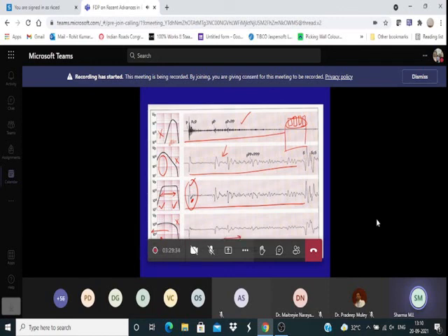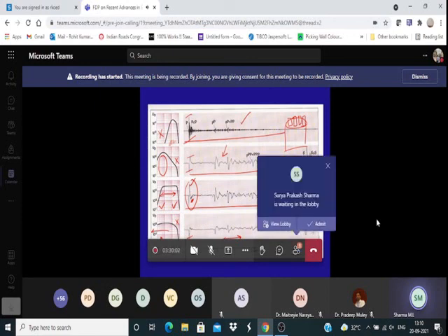So what I want to show here is that a single earthquake is recorded by many seismometers of different characteristics, and therefore the amplitudes are different. And you know the magnitude is defined based on the amplitude. So it means that you have to have a common definition of the earthquake. And fortunately, this definition was given in 1935 by Richter based on the Wood-Anderson standard seismograph.